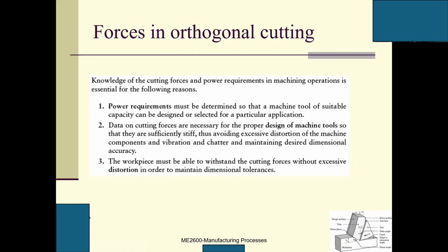to do some work. So knowledge of cutting forces and power requirements in machining operations is essential for the following reasons. Why is this very important? The first one, the power requirements. If you want to generate the final products, and for a very hard material, you need to know the power requirements. If this material is very tough, maybe in our machine shop the power cannot satisfy this requirement. If you do it, immediately the fuse will be blown. Right? So you need to know the power requirements.